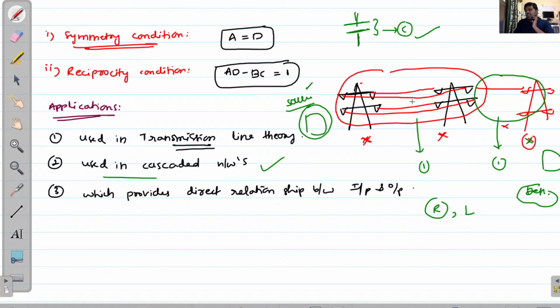In these conducting wires also, which are separated by a certain distance, we get capacitance. These all three are not present directly here, but they are involved in an indirect manner. These are hidden things. While making this construction, these values are not directly present, but indirectly these elements are involved in this particular construction. These hidden RLCs are called parasitic effects: parasitic resistance, parasitic inductance and parasitic capacitance.